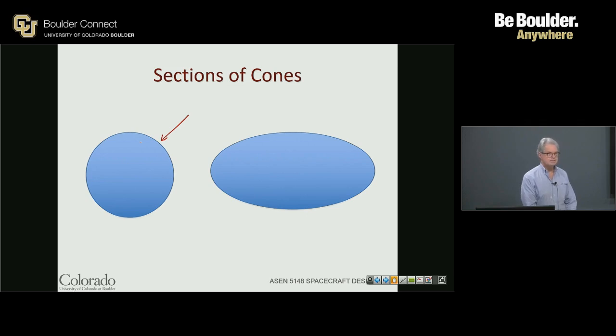And the reason for that is that when you look at the properties of planets, not only are they not spherical, as I said, the Earth is an oblate spheroid, but mass is not uniformly distributed. Gravitational attraction around the Earth, in particular, varies as a result of where we are. So think of flying over the Earth with fixed gravity. That wouldn't put any additional force on your spacecraft. But now imagine an Earth where gravity changes at each location. You've now got your spacecraft speeding up and slowing down, speeding up and slowing down. And that does certain things to the overall orbit.